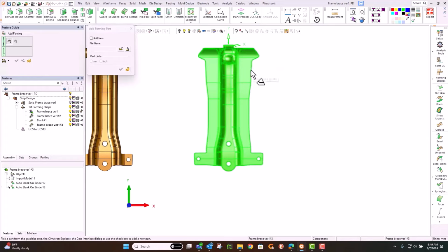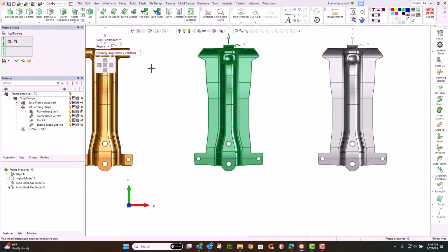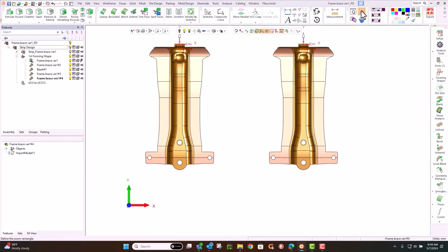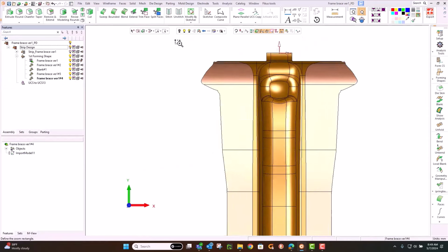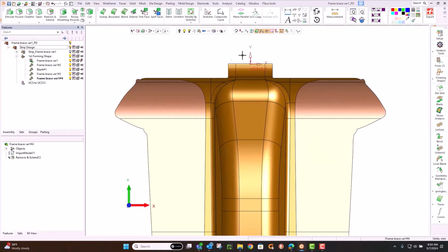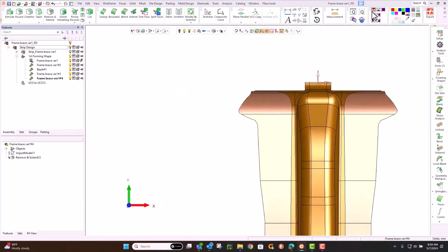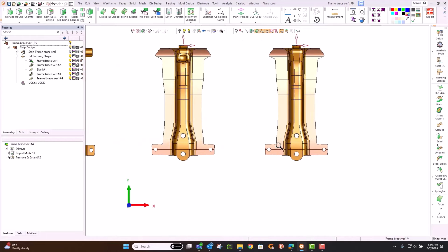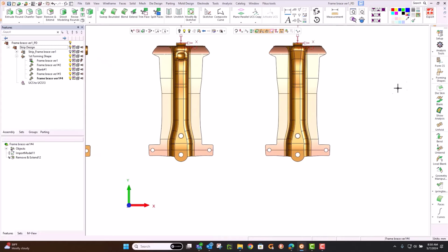Here in the center, you see there's a dimple. Right, so perhaps that was placed in because we needed to stretch that area, understanding that there's the wrinkle tendency. Let's do that in one single step. So in this case, we'll go ahead and take that out of our sequence of operations. Now we've got our forming condition just for that particular dimple area. Moving on, we'll do another one.